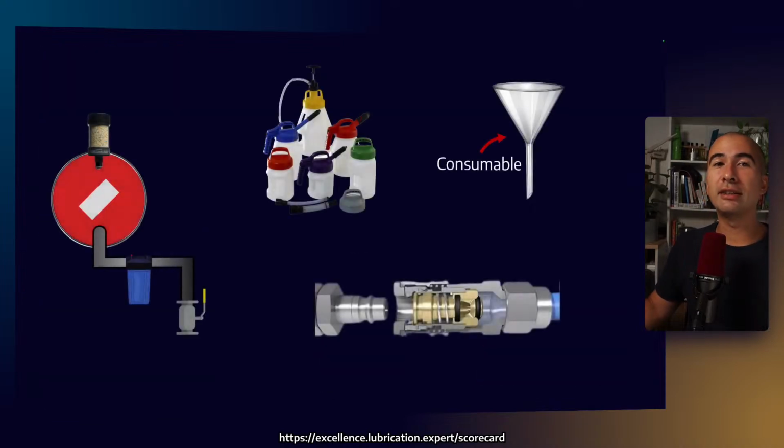When we're using containers, the general rule is we want to filter whenever we are doing a transfer. We want to use closed containers, and any funnels that we use are considered consumable for the purposes of our equipment. So using funnels is generally discouraged.